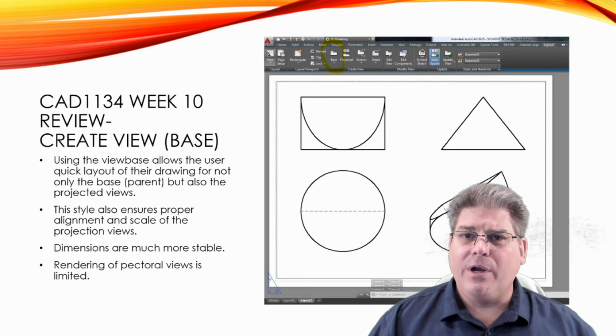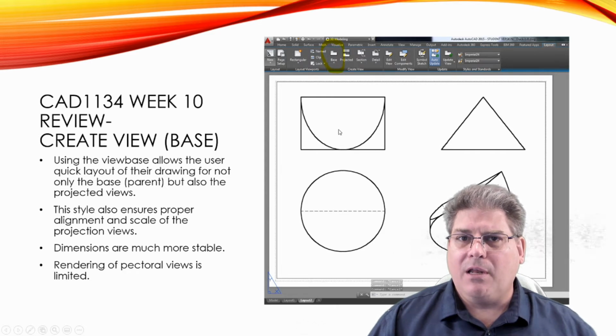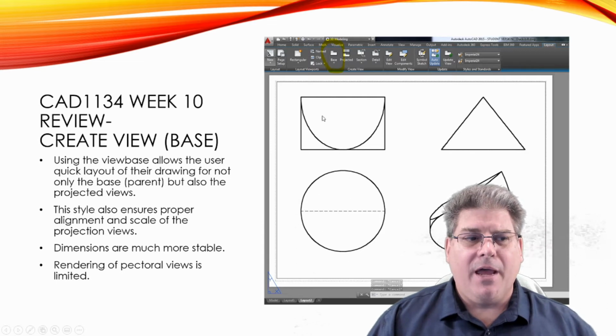The other way to create a layout is to use the base, and we can easily lay out perfectly aligned geometry like this. So here's my valve bill. We're looking at the front face, the bottom face, and the side view. And the nice thing about this is it does do the first and third angle projection automatically for us, so we know that it's right.